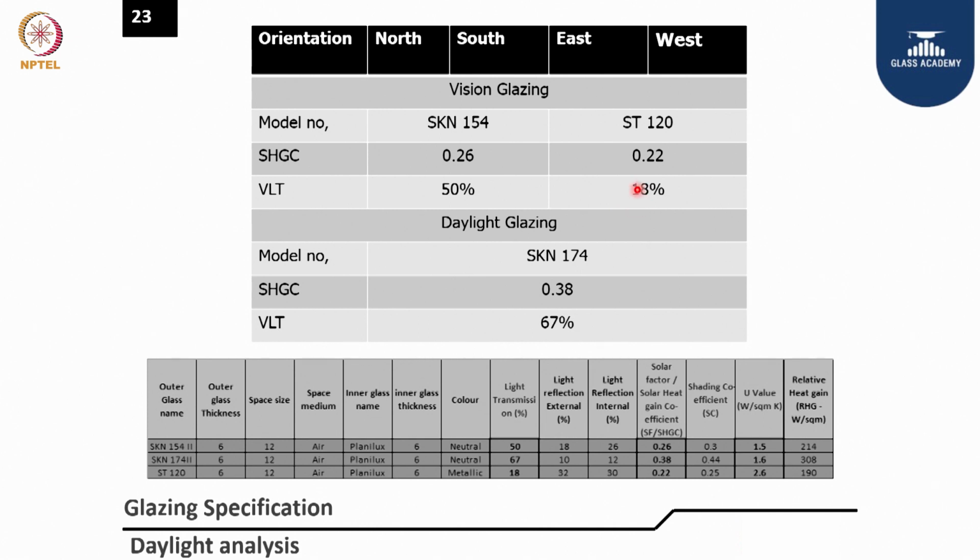gain. So two layers: a little relaxed one for the upper portion of the wall, to get the daylight penetration without blinds, and the lower portion will be a little more efficient glass. In that way you can optimize the daylight and glare for an indoor environment.